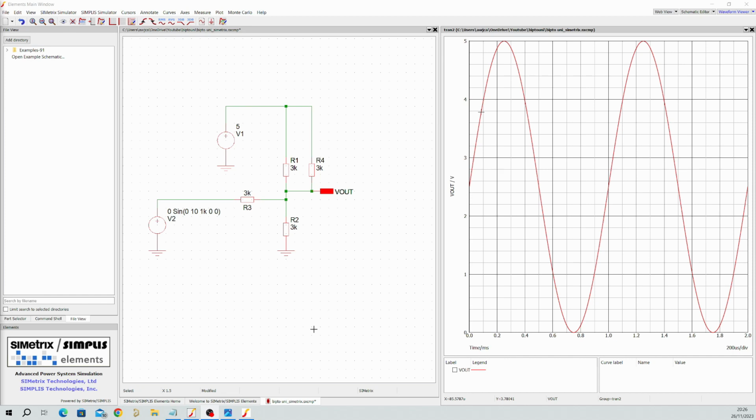With regards to the voltage divider and the attenuation network that you're seeing on the screen now, and it can be any voltage divider, it could be an enable or one on a comparator, it could be a voltage setting for a power supply, if you want good tolerancing of that function, place all the parts on the same side of the card next to each other.